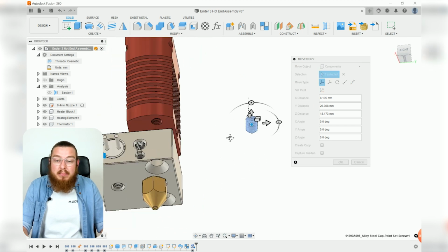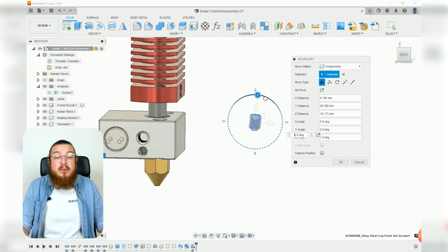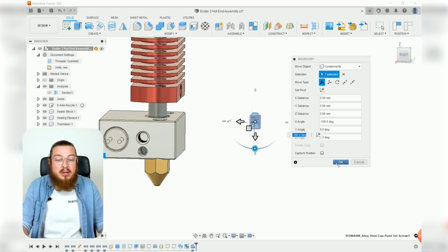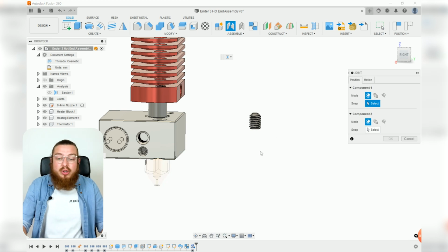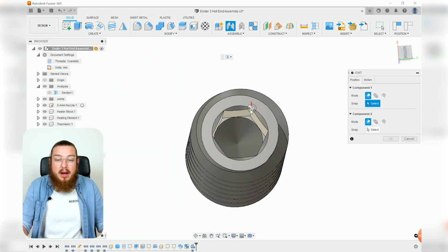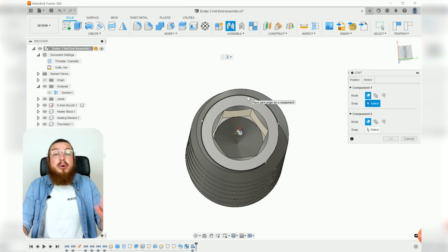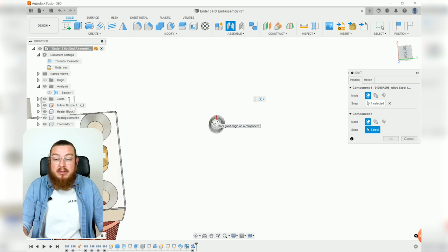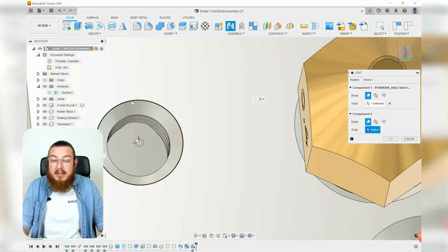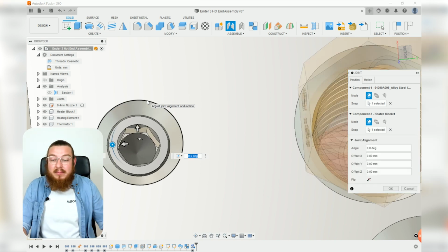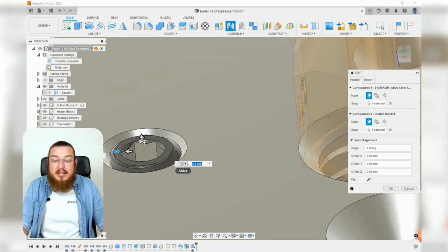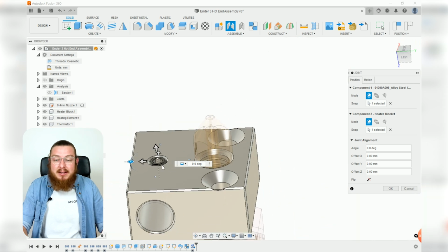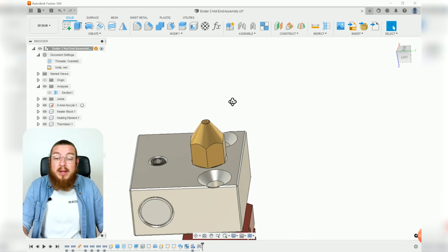So we can just pull this out. We can be starting off by putting this in the underside first. So if you want to, we can rotate this so it's about in the right orientation. And then we're going to type J for joint, and we're going to select somewhere on the outer ring, so it puts the joint origin right in the dead center of that circle. Then we can move over to a similar place and select the outer ring of the circle, so that, there we go, it slides in perfectly. This is actually set to slider from our last fire piston project, so I'm going to change this over to rigid. There we go, kind of shakes, which means it is fully cemented in place. That's perfect. So we can just click OK.